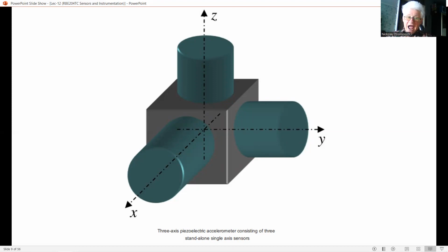More recently, MEMS 3-axial accelerometers have flooded the market, mainly for consumer products like cameras and games. They are also available with integrated interface circuits. Typical sensitivities are from 10 to 100 millivolts per G, and weights from 10 to 50 grams.